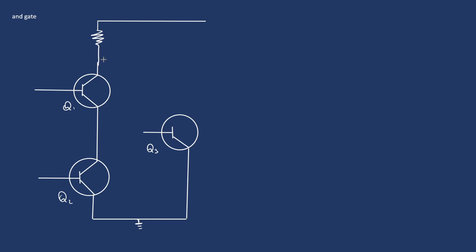and then we draw our circuits, and then from this node of our load resistor and Q1, we take that right into the input of Q3. Okay, that's this way and that way, and then the same thing happens on this side. We're going to raise this up to positive 5 volts, but it's going to need its own load resistor. Okay, so this is a rather big circuit, you can make yours shorter as need be.